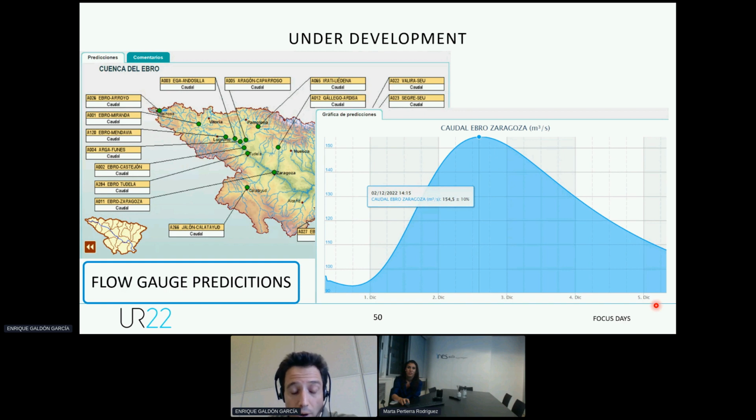That is quite interesting, because if you are able to establish a threshold limit for the flooding, you can go further up and limit that, and then you have a 5 day prediction that can tell you when you are going to achieve that limit, if you ever achieve it, and then when you are going to get the inundation further down. So you can get 5 or 6 days of prediction, plus the time that the flow reaches further down.